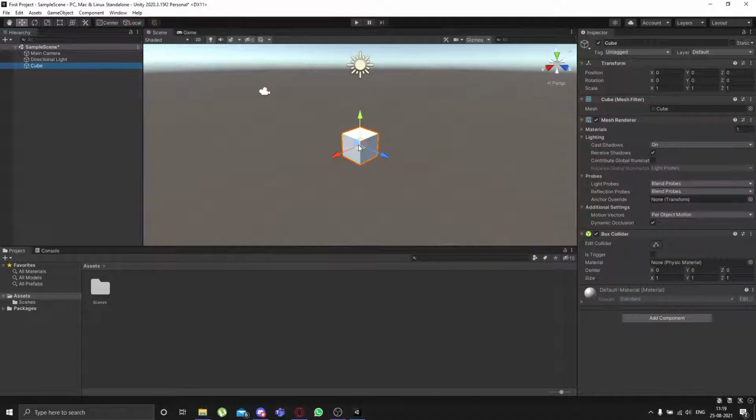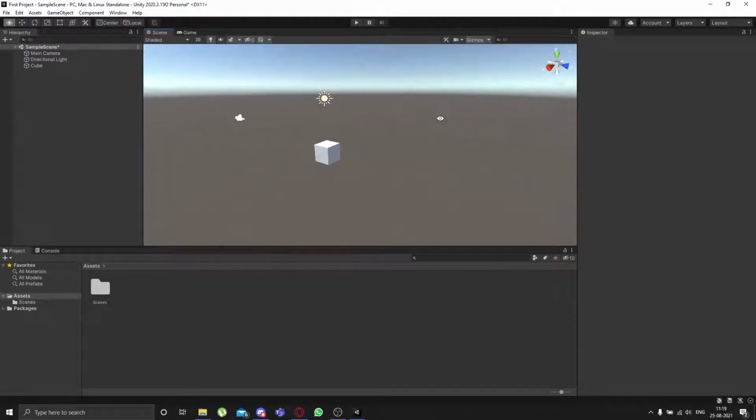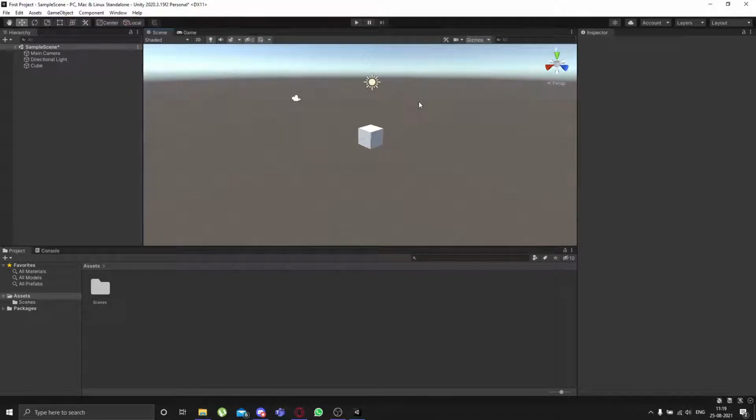Oh right, I just zoomed in without telling how I did that. So to move the viewport around, you can use the scroll wheel to zoom in and out. Hold the scroll button down and drag, so that you can shift your view perspective, and right click and hold drag, so that you can rotate your view.